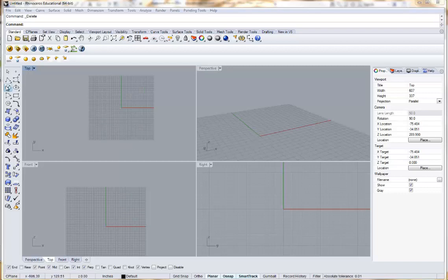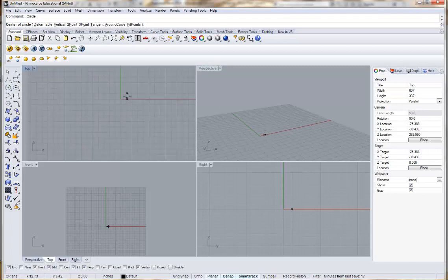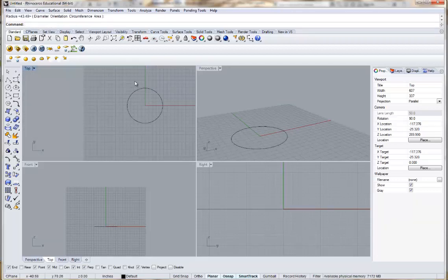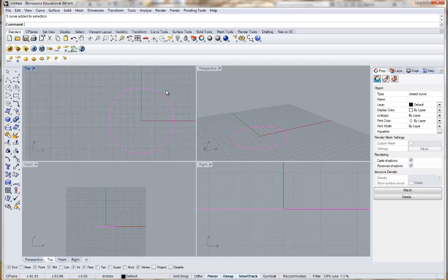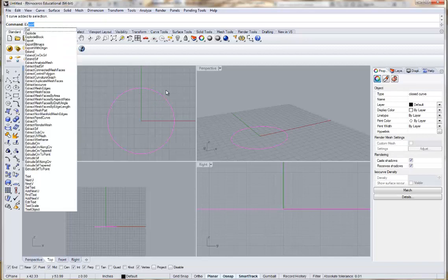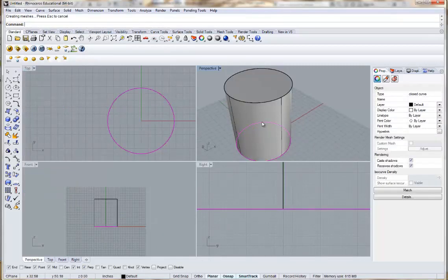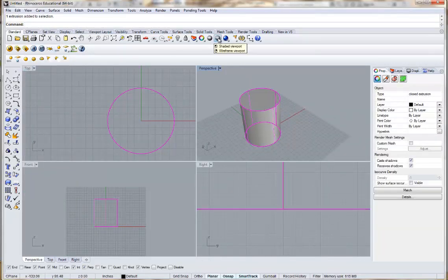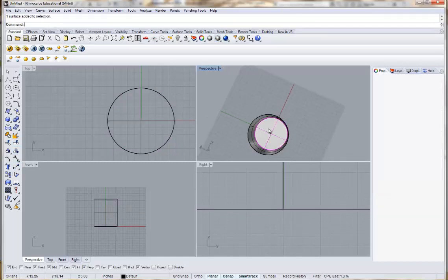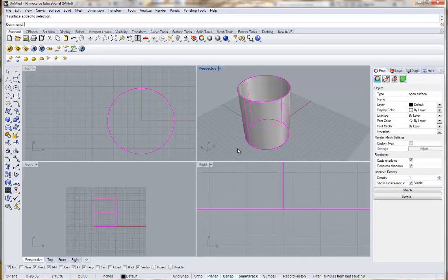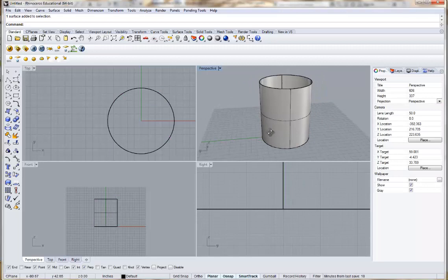So the first thing I'm going to start with is to create, assuming that we're going to generate a wall structure around a spiral staircase, imagine a staircase going around this. I'm going to model the interior wall, and I'm just going to extrude that curve. I won't use both sides. I'm going to take that and first explode this. I only need the geometry of the actual surface to generate the construct that I'm trying to develop here. At this point it's essentially ready.